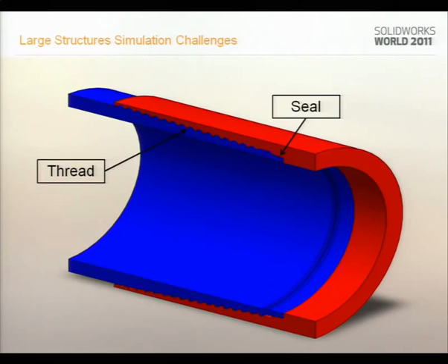So this is the actual model. One of the application engineers and I tried to run it in 3D with a 3D model, and it was impossible. It takes a lot of time. It was not stable because of the contact; it was impossible to solve the contact. So now we have the new capability, 2D simulation, and the question here is, which of those three options is it? Axisymmetric.